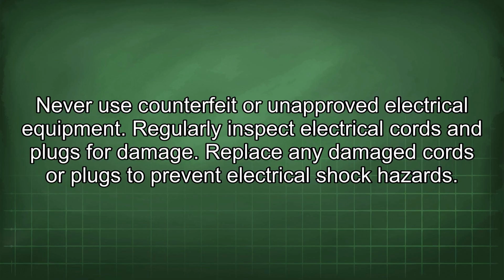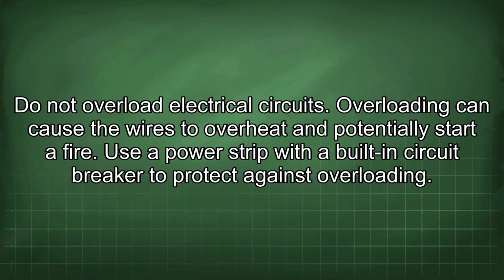Regularly inspect electrical cords and plugs for damage. Replace any damaged cords or plugs to prevent electrical shock hazards. Do not overload electrical circuits. Overloading can cause the wires to overheat and potentially start a fire. Use a power strip with a built-in circuit breaker to protect against overloading.